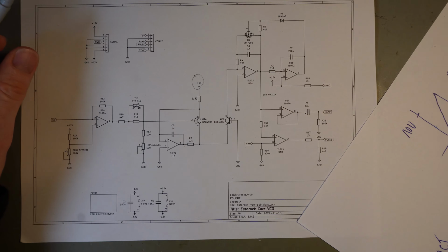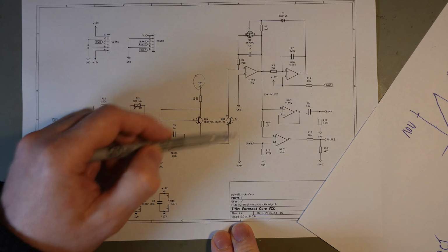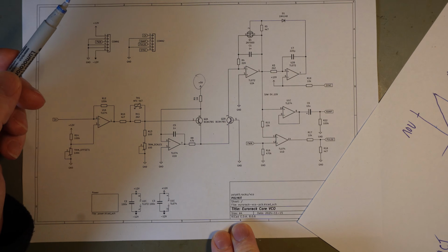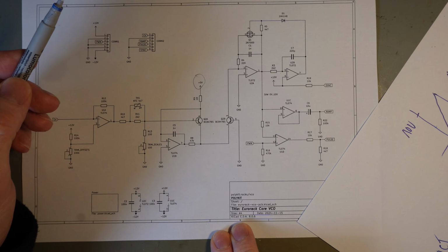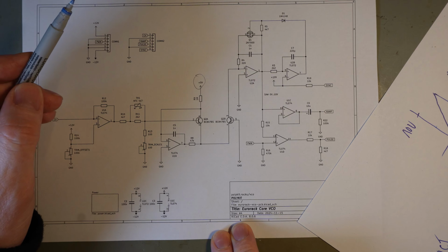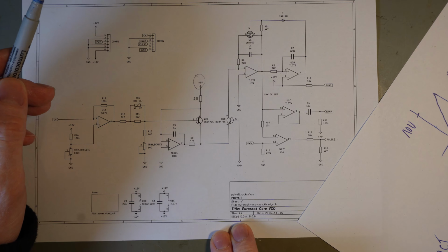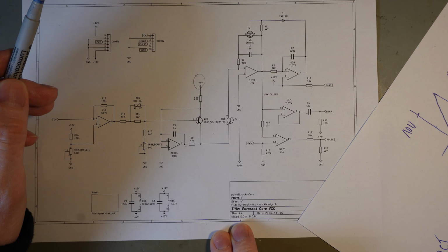And to achieve this in these old designs, you usually use matched transistors here, so they need to be matched very precisely. And what really is an issue here is that we are already at component tolerances, which really was an issue back in the 70s. So what the manufacturers did, they pre-selected components which they put in their synthesizers. But in terms of mass production, this was really a problem.